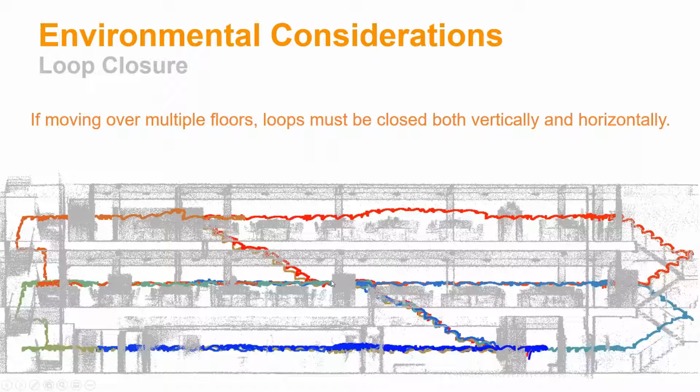Again, a recommended start would be somewhere in the middle if you're doing more than one capture. So you do one loop, finish the scan, and do another loop, where you have enough, about 20%, overlap between individual scans for merging at the post-processing stage.